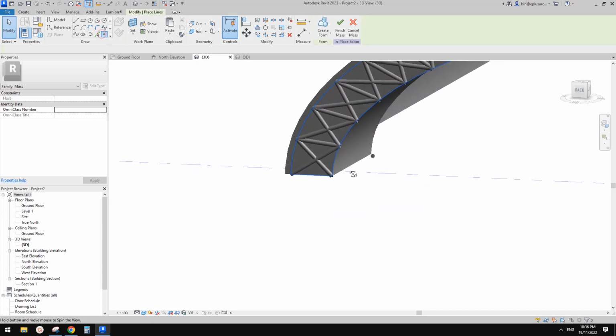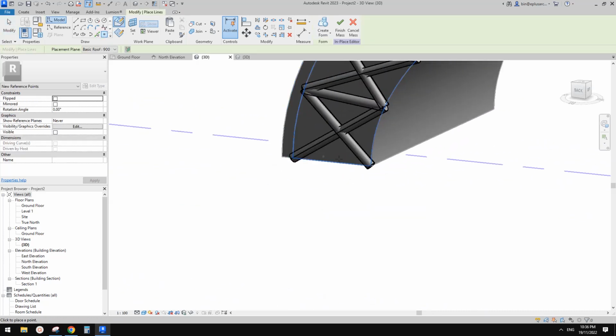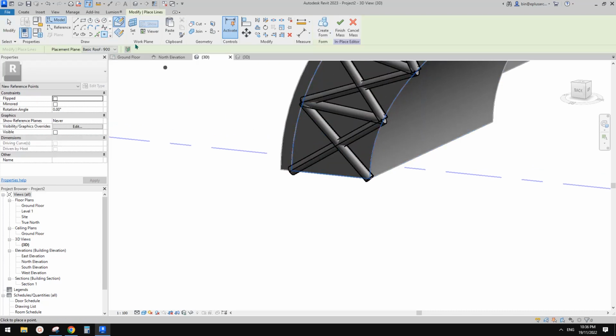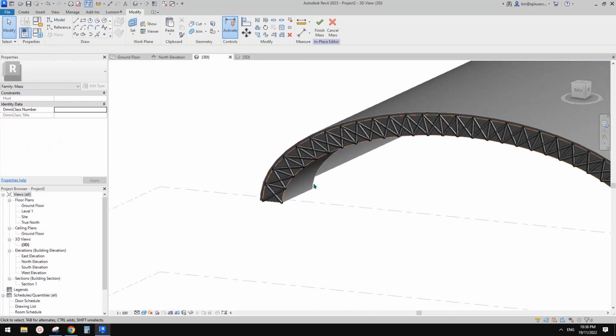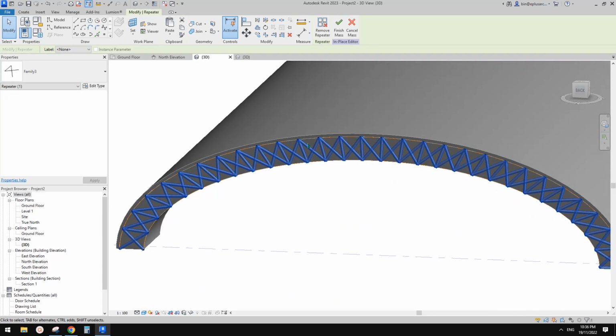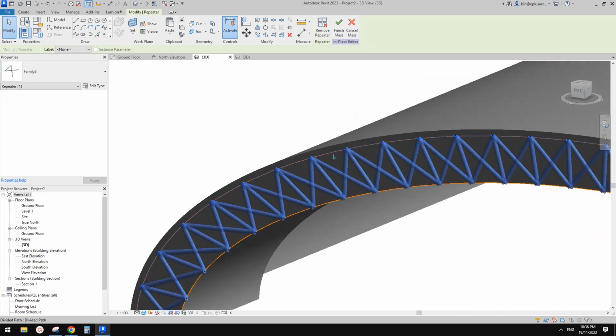You might need to just place a point on this reference line, place another point on this reference line, and connect them. Use spline through points, and then place a point, place a profile, create a form. Okay, so I'll leave it to you. So then for this one, exact same.